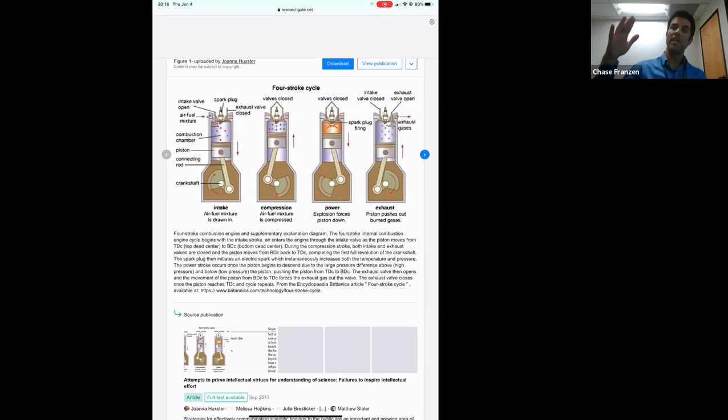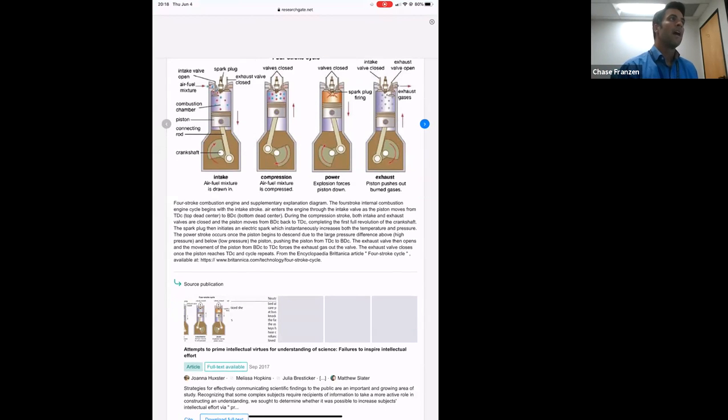And that's why as we climb in this aircraft, you produce less and less power as you get higher and higher. That air is thinner. You've got fewer air molecules. And so the engine performance subsides as you climb. It's direct drive, meaning that the propeller is connected directly to the crankshaft. And again, it's 320 cubic inches. So that's the engine that you have in this airplane.